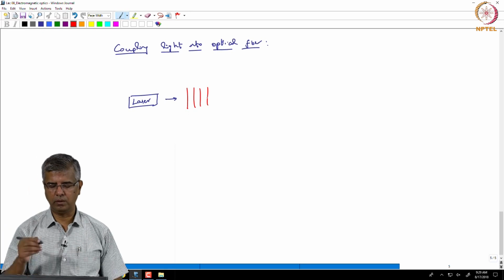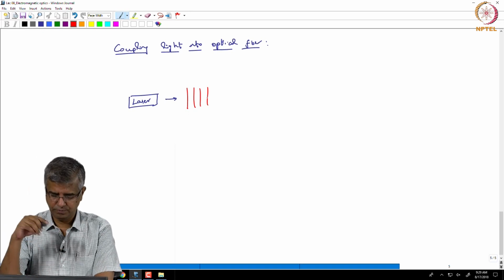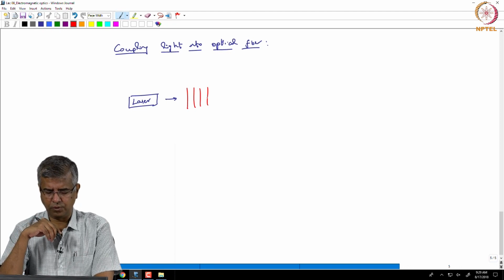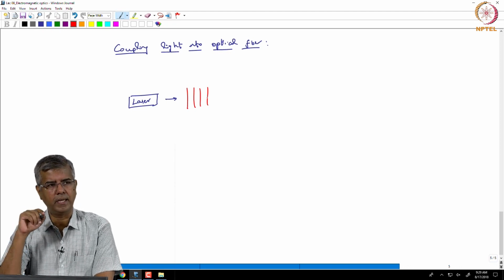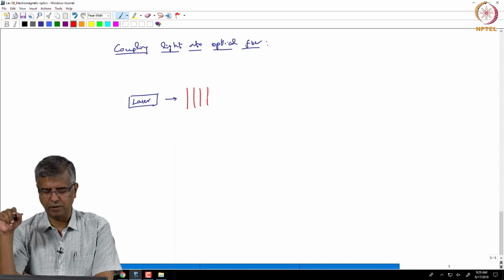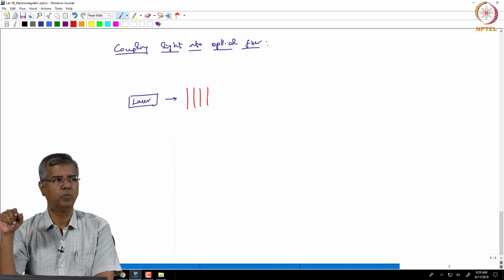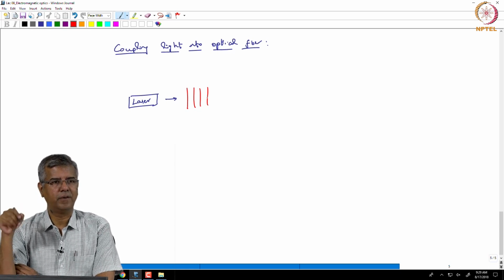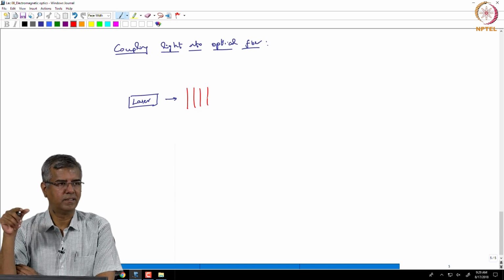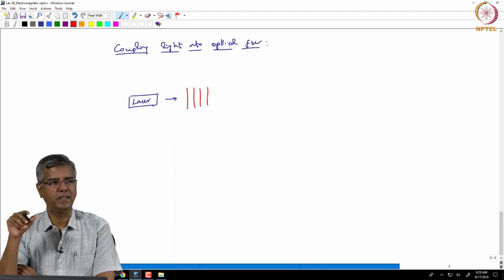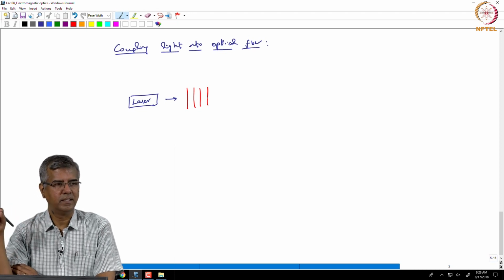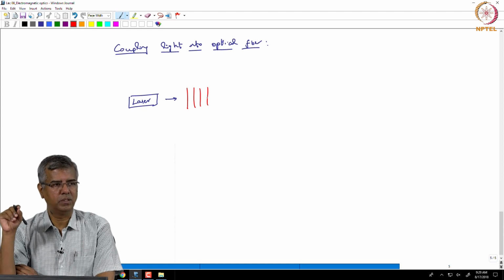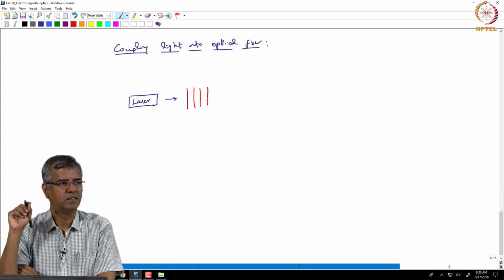The laser that we have has a radius of a few millimeters, but then it has to couple into an optical fiber. Let's say we are coupling into a single mode optical fiber. Okay, what is the size of a single mode optical fiber for the wavelengths that we are considering? It's in the order of few microns, right? So a few millimeters need to be fitted into a waveguide which is a few microns.